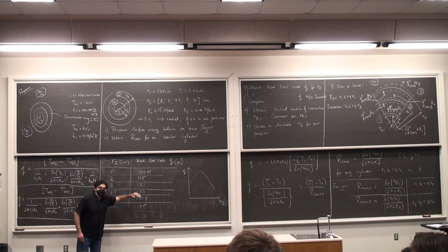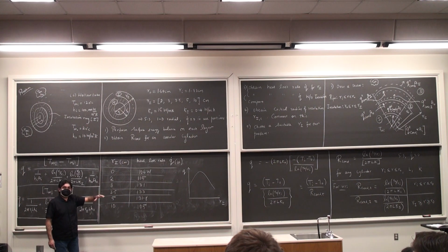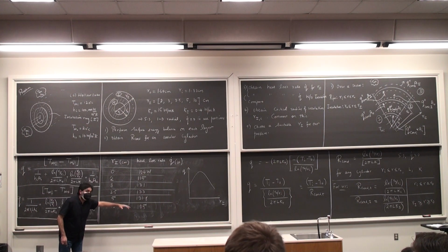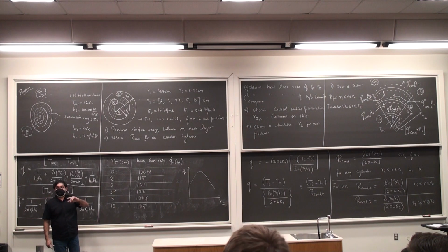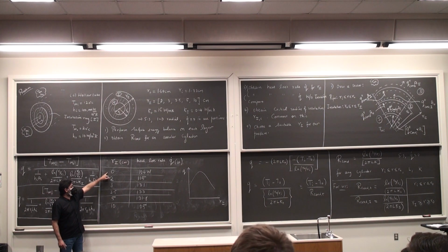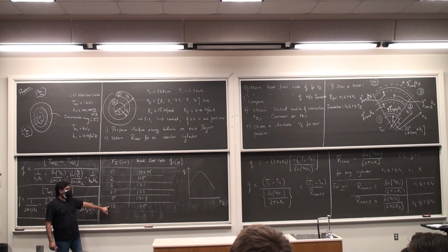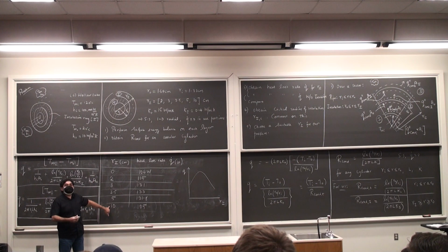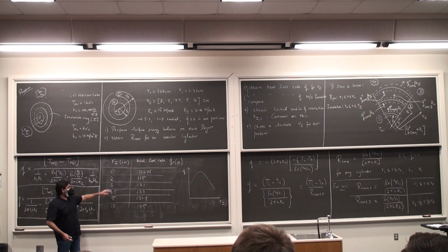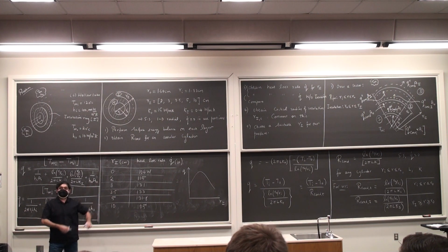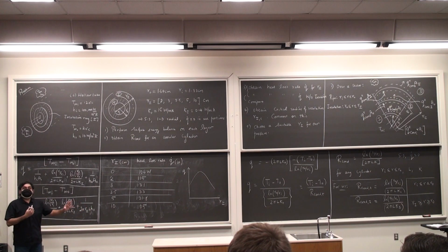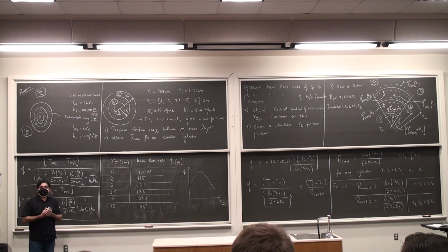And it's only after you go beyond that critical radius of insulation, the heat loss rate is going to start reducing. And depending on what your calculations were with the case of no insulation, you will have to go up to maybe 10 centimeters or more to actually start having any usefulness in putting in insulation on the system. If you decide to buy insulation for 2 centimeters and have it for a length of a pipe of 2 meters, you are wasting your money and your time. You might as well just not put insulation on it.